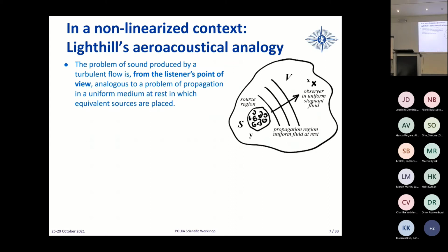That's a general problem of the wave propagation equation: if you have your wave propagation operator and a right-hand side, there is an infinite number of ways to formulate a right-hand side that will give you the same measured acoustic field. There's the whole problem of inverse methods like acoustic beamforming and all those techniques where you try to guess what the source field is from a certain acoustic measurement. This is a problem that is fundamentally ill-posed because you have plenty of ways to distribute sources that will give you the same acoustic field.